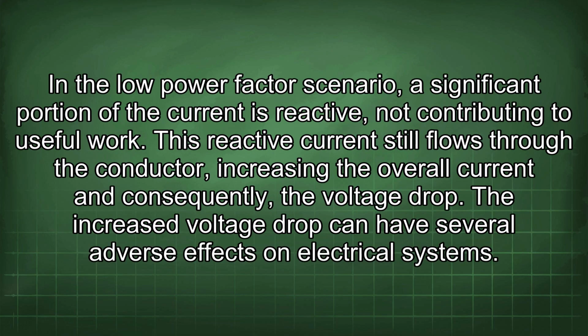In the low power factor scenario, a significant portion of the current is reactive, not contributing to useful work. This reactive current still flows through the conductor, increasing the overall current and consequently the voltage drop. The increased voltage drop can have several adverse effects on electrical systems.